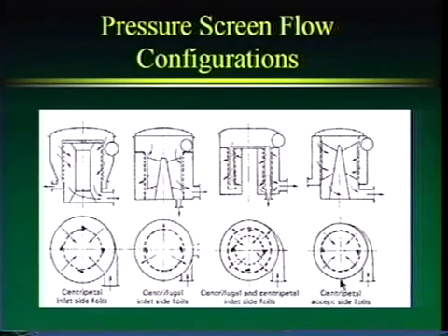And then we've got another one where, very interesting, we have our feed on the outside, and the pulp is going on the inside. And then the foils are now on the accept side. So they've got to do their cleaning by working on the accept side. The lead edge of this foil is going to push fiber backwards and give that backflushing mechanism.